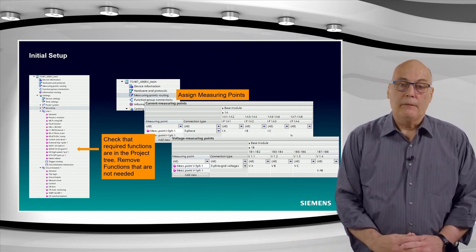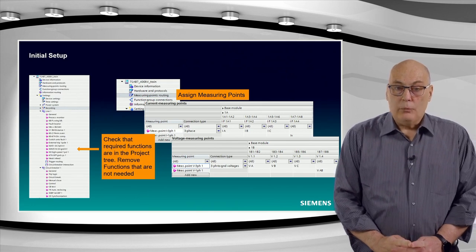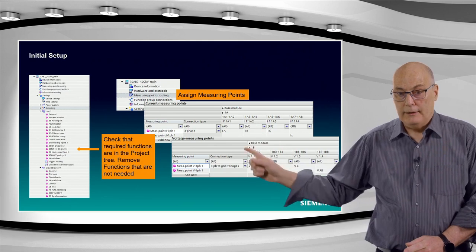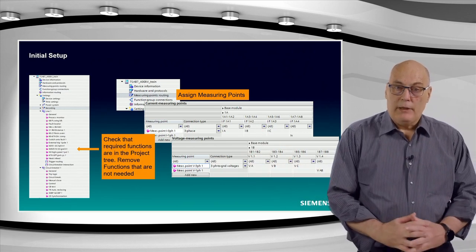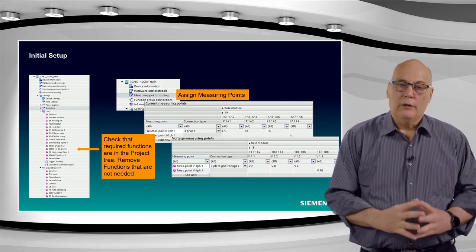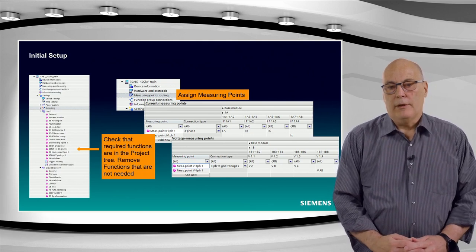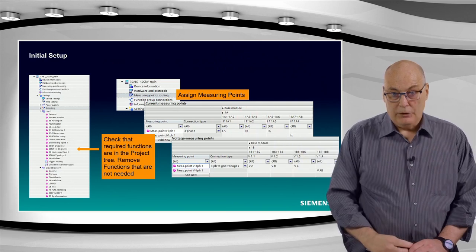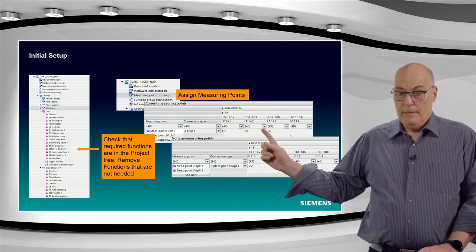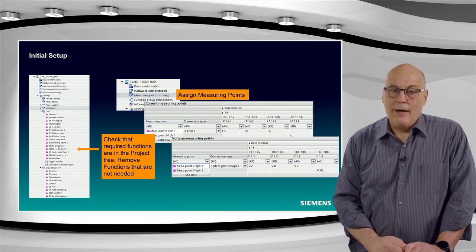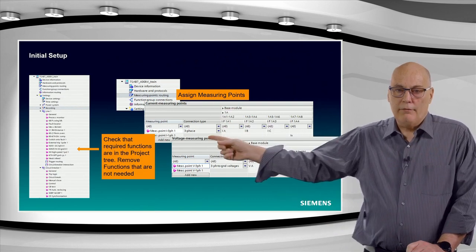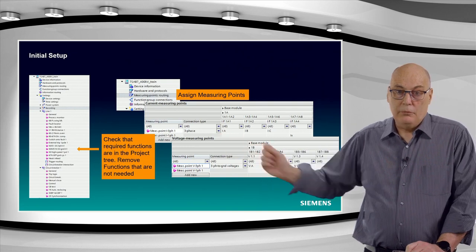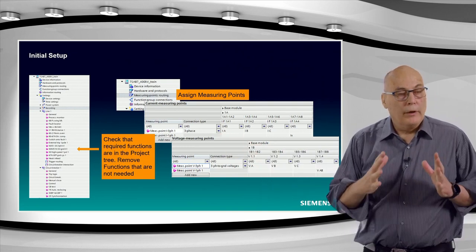That is that point. The other thing we have to always see is the CT-VT connection. That is another key aspect for the relay. If you're going to apply that, you have to make sure that the CT and VT are connected to the function. That is done in the DIGSI configuration under the measurement point routing. You can see here, physically in the middle, the current measuring point. I have defined here two current measuring points. It's interesting, the one, a three-phase current measuring point, is going to be the one connected to the protected line.